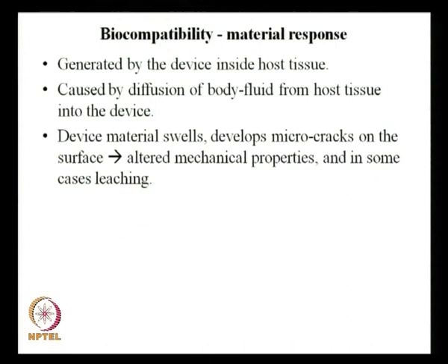The body fluid is there and you have inserted this material inside the human body, so the material is coming in contact with the body fluid. Now, if the body fluid diffuses into this device, then the device material swells. That is the third point I write here.